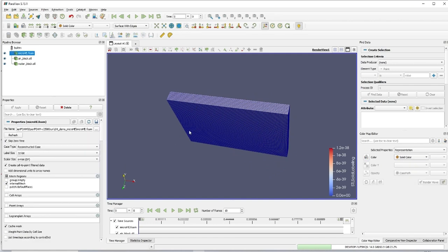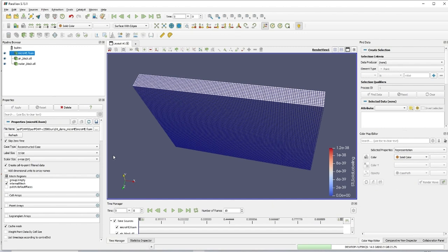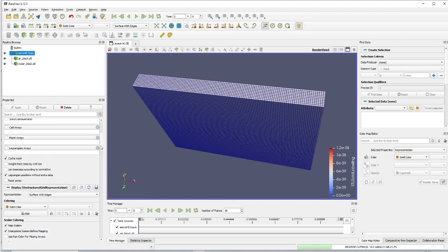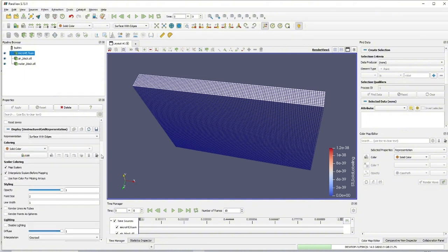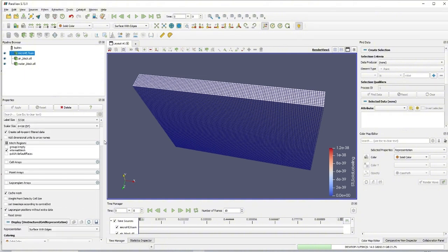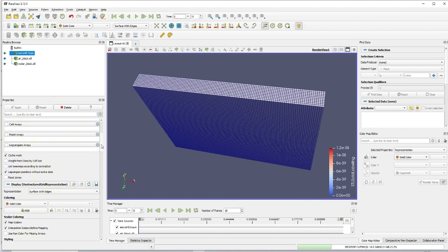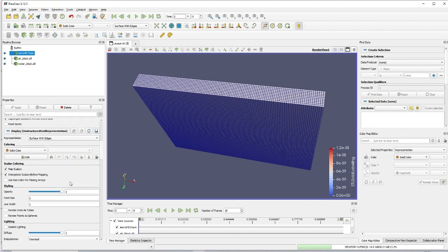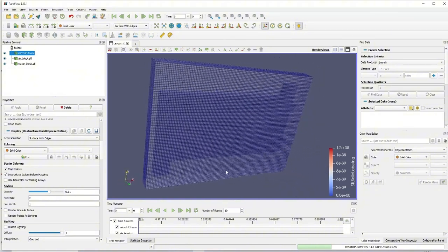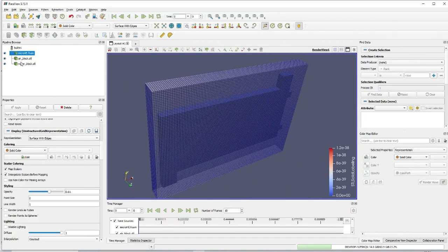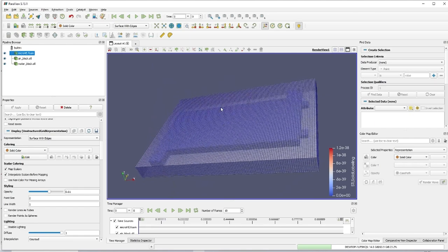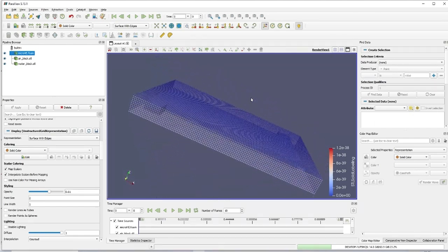That's because my background mesh, if you still remember, is bigger than the mesh of the STL file, and that makes sure they cover all this, but also because of this, we can't see clearly what is inside. How can we do that? We can change the opacity of this background mesh. So if I make it a little bit transparent, I would say our air block and water block have been included in our background mesh, right?